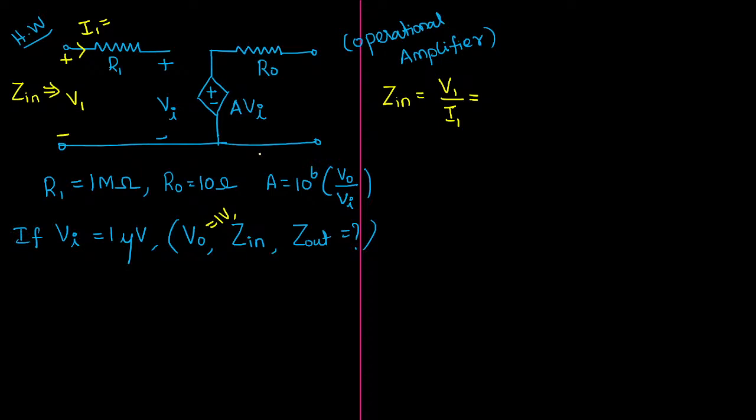The value of I1 should be 0 ampere. Good, very good. See, why is it 0 ampere? Sir, again same concept. After reaching this junction, if you are trying to inject any current here, that current will come up to this point. After that, where will it go? Since this port is open circuited, do you have any connection here? It is simply open. So then how will current go? So I can say the value of I1 will be approaching 0 ampere.